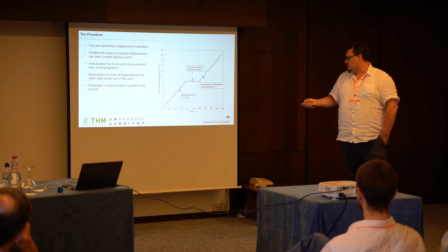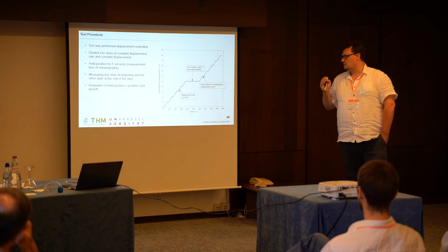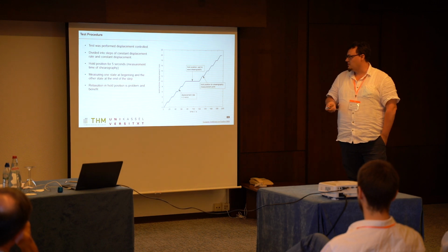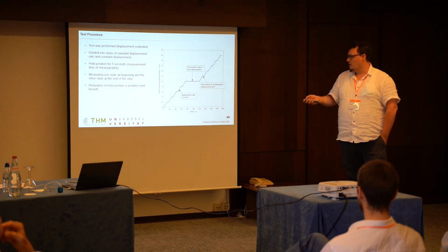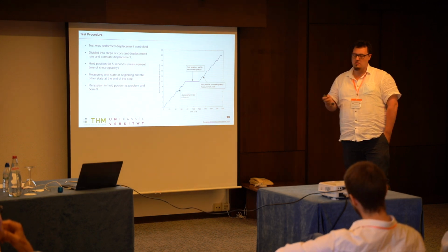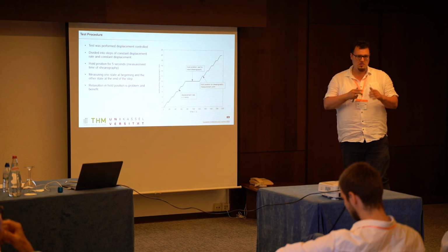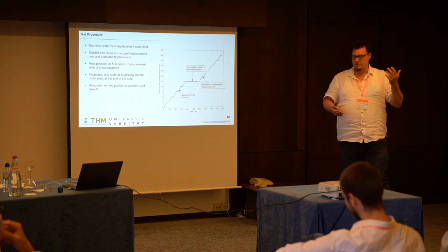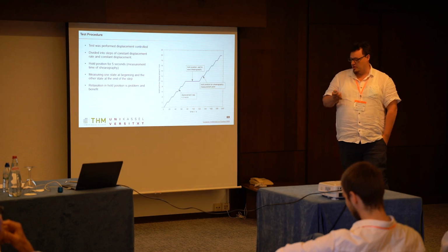Now some words about these plateaus. This is caused by the shearography system. I think you will hear more later. Also, during this hold position, relaxation occurs. That's on the one hand a problem for the J integral measurement, but a benefit for the shearography measurement.